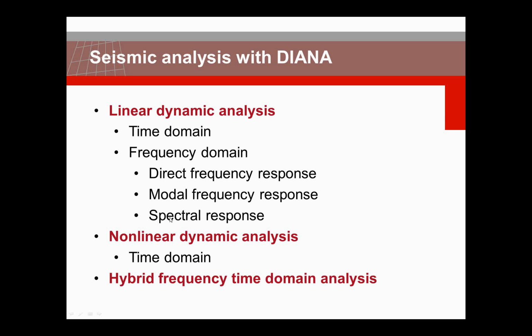And the frequency domain has some advantages because usually it is very efficient and you can define some damping parameters as a function of frequency. For example, compressibility of the fluid or the bottom absorption of fluid in a dam, which is important. On the other hand, when you want to consider the nonlinear behavior of the structure, you cannot use frequency analysis and you should use transient analysis, so analysis in the time domain.